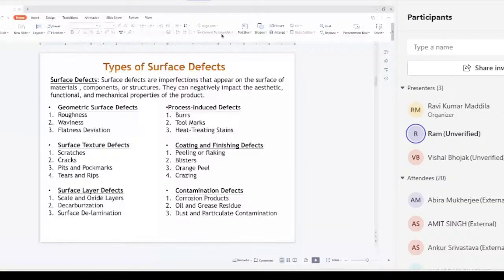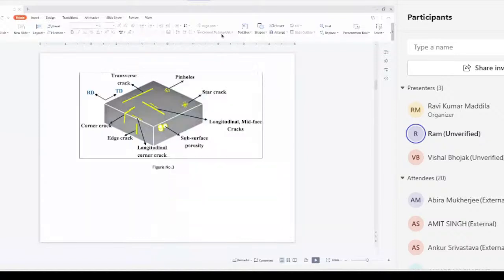And there are different types of penetrants. If I use fluorescent, it is type 1. If I use liquid dye penetrant, it's type 2. If I want dual, it's type 3. Different types of penetrants are used in the industry depending on sensitivity. After application of the penetrant, you have to remove it, either with water to clean it, or solvent to remove it, or post-emulsifiable. If you want higher sensitivity, people go for solvent removal.